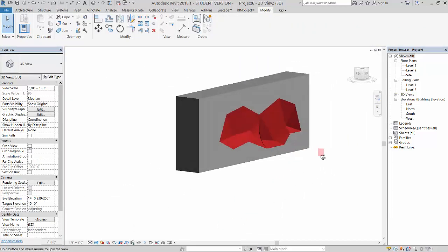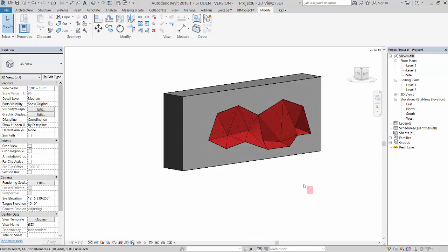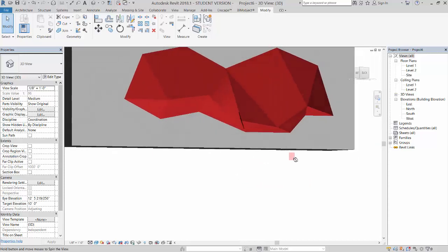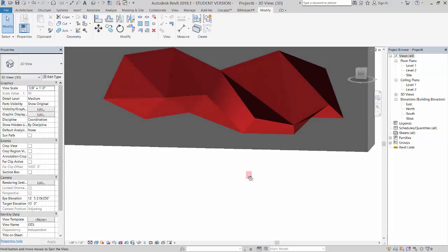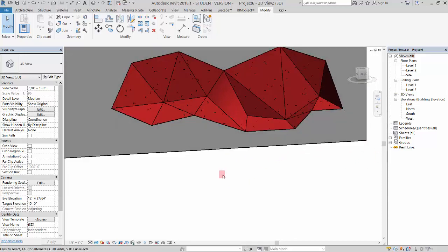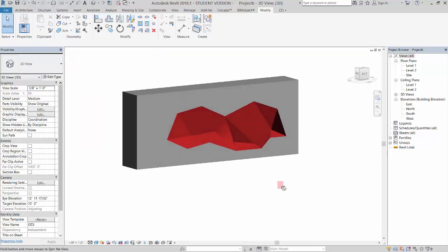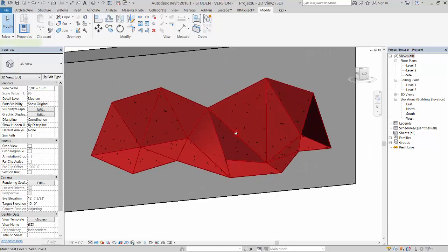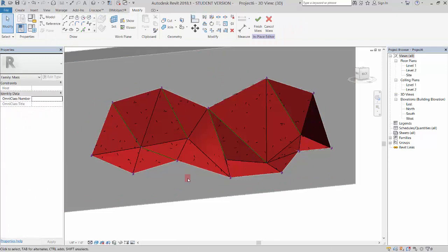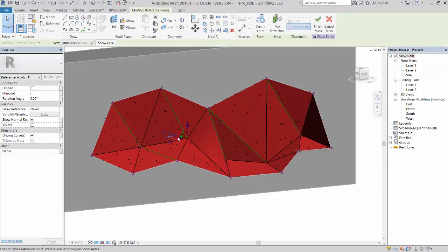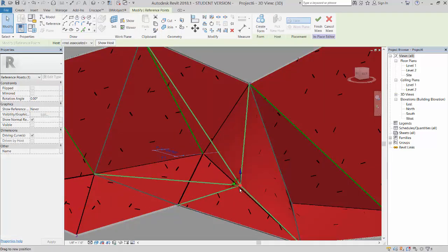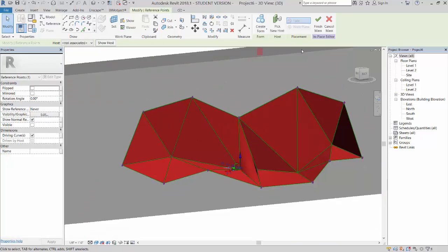So now I've got that material applied to it. So you can see how that looks. Okay, and then you can also see it twisting the rectangular ones, so you have these sort of rectangular twisted ones, and that's probably how I would do it. Now you also still have access to select this and go to edit in place, and those points are still movable. So if I just pick that point, I could actually pull it out, so it's outside the wall.